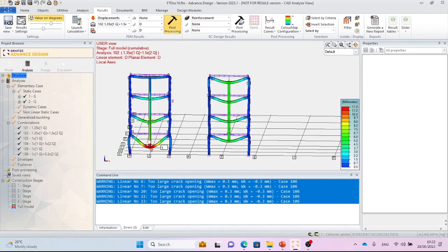So when adding the construction phases, we see that the beam of the first floor has deformed more compared to the beam on the right-hand side, where the deformation is almost half of this on the left-hand side. And obviously, we can see that as we climb higher and taking the second, third, or fourth floor, the deformation tends to become smaller and smaller.